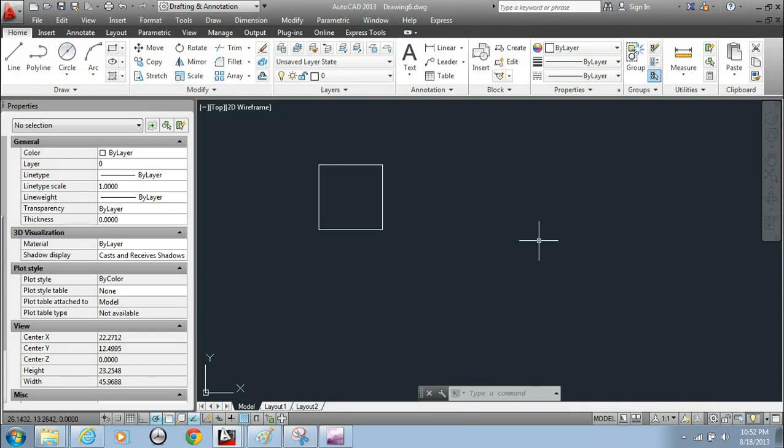Easy enough. Go into the line command. Now, let me get that implied intersection sort of thing. So I'll go near my endpoint here when I see my snap, and then I'll have my polar tracking turned on. So I want to see that green line. Now, you don't have to do this, but I'm just trying to line mine up. So just somewhere in here, I want to left click.